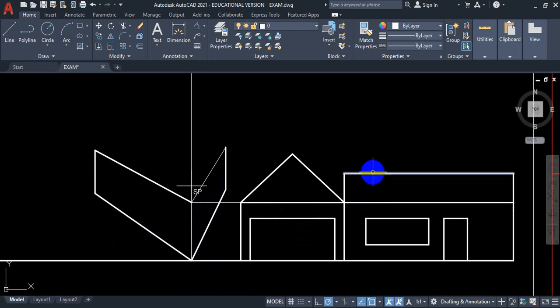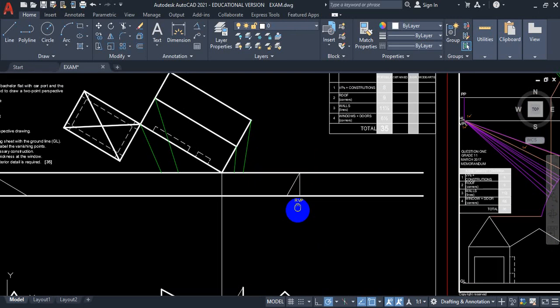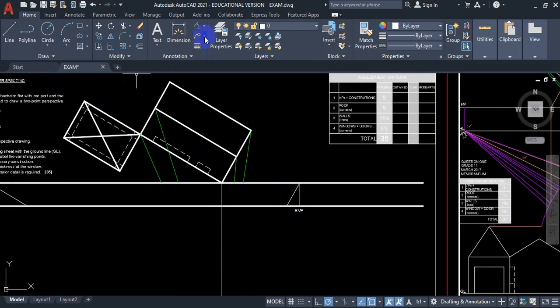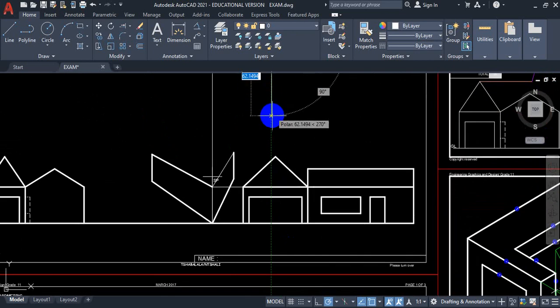Now, your house needs the roof. All right. How then do we get the roof? There is what we call a height method. You have to extend this line to picture plane. So I think don't you bring it down on the other side? Picture plane. Extend it to picture plane. From picture plane, draw a vertical line. Remember, you are looking for this height here.